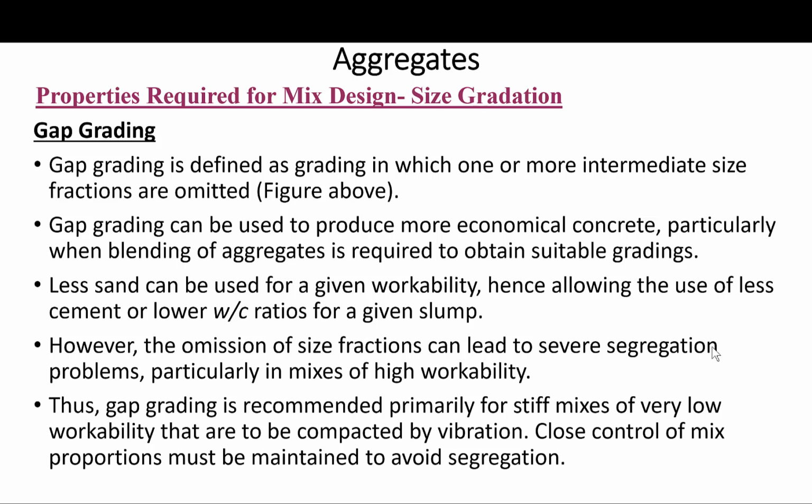So adequate fine material is needed for good cohesiveness and plasticity. Remember that. So the 10% passing the 300 micrometer, number 50 sieve, allowed by ASTM may not provide sufficient fines for hand finished concrete floors, or when a smooth surface texture is required.